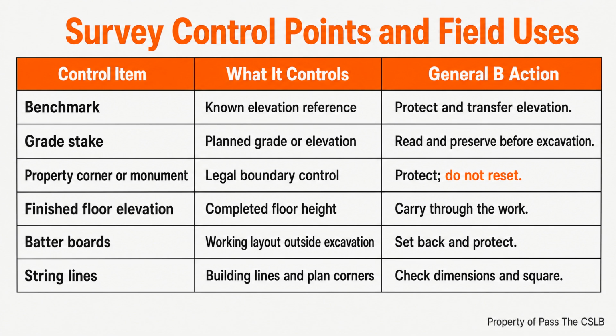After a boundary monument is set, reset, or referenced, the licensed survey professional has the filing responsibility for the corner record within 90 days. That filing is not a task the general building contractor performs. The contractor's responsibility is coordination and protection, especially before the point of disturbance. The simplest way to avoid a costly mistake is to include survey control in the pre-construction conversation.